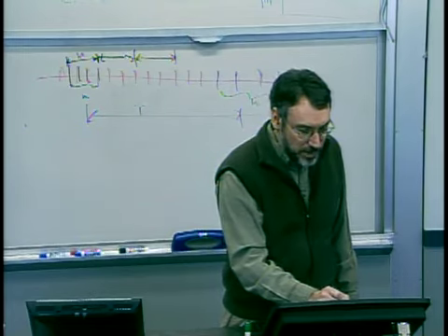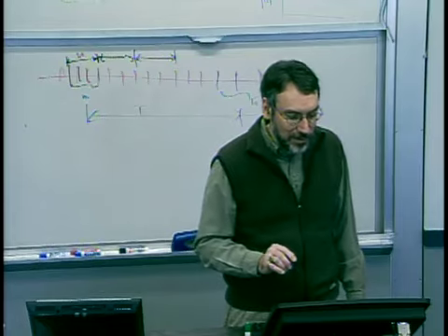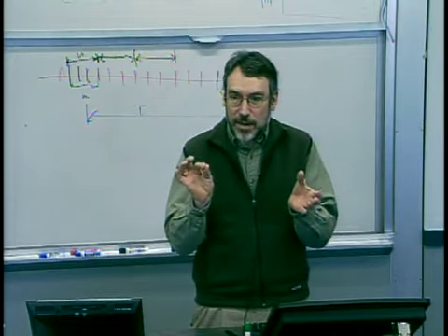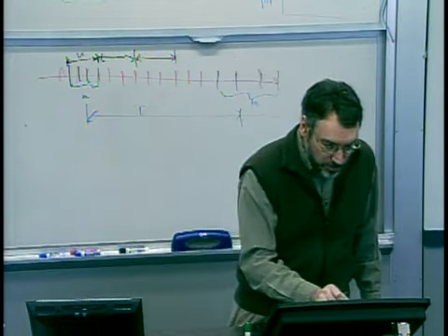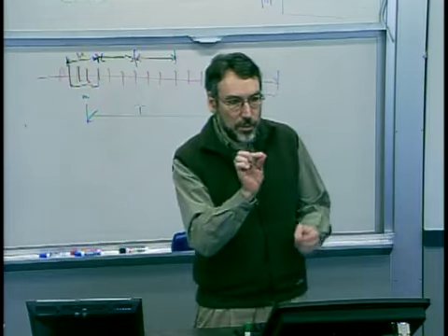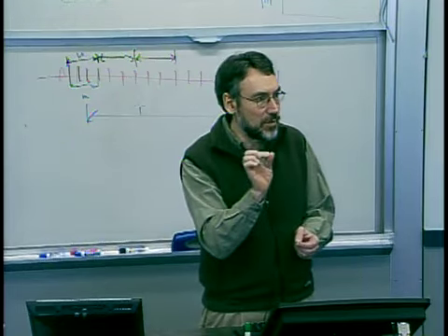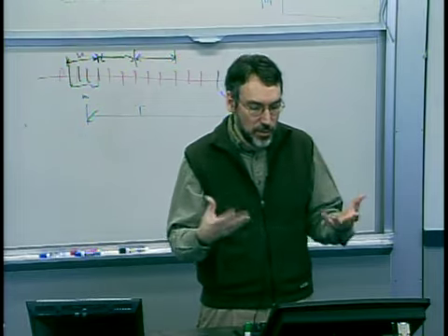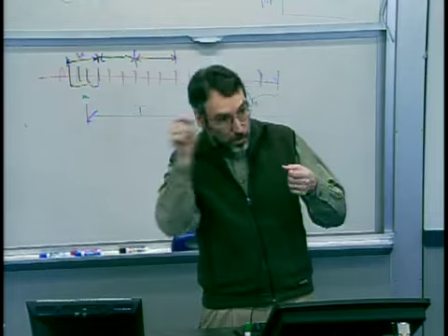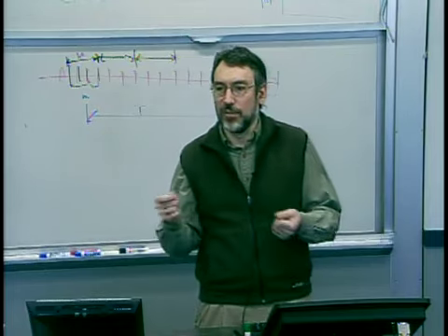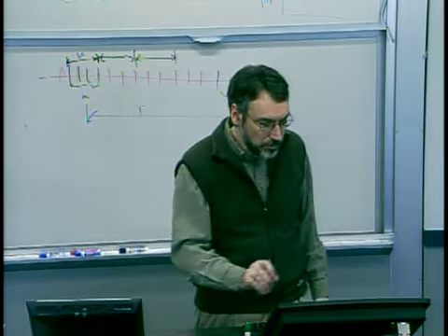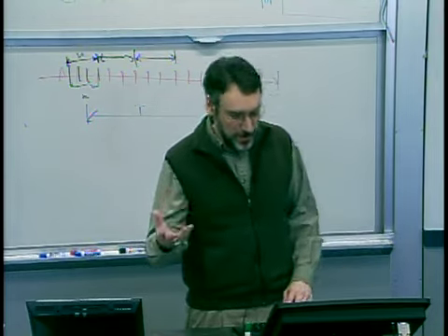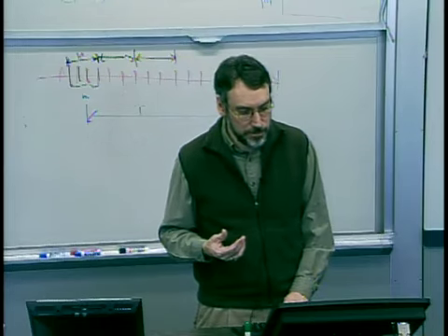What you get is one component that is clearly related to your variance in the process, and another component that is clearly related to your mistargeting or deviation from the mean. So in one quality loss function, again, you can see and relate in the normal distribution sense how both variance and target deviation contribute to quality loss.